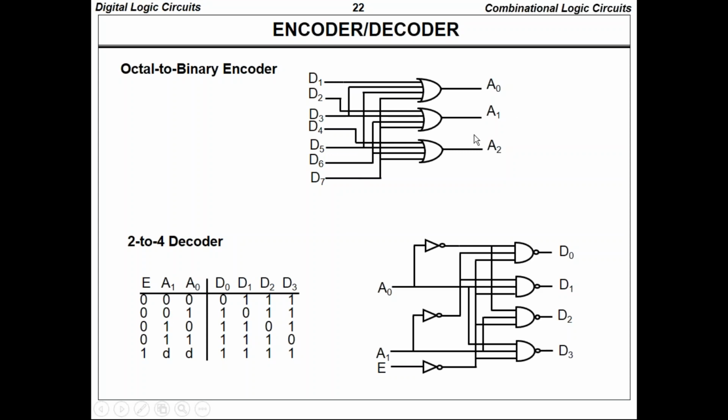So like that the expression will come. So only thing, if we know the functionality, we just use the truth table to convert the input and output logic. Then afterwards, through the K-map simplification, we are reducing the expression. Then after drawing the logic diagram, we are getting it like that.